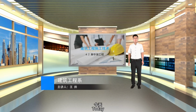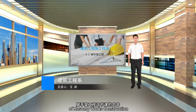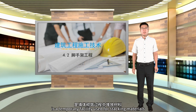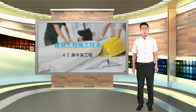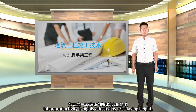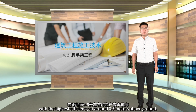Hello, everyone. Today, we will study scaffolding works in the chapter of masonry works construction. Scaffolding for masonry is a temporary facility used for stacking materials and providing a working platform for masons during wall masonry construction. When workers lay bricks on the ground or on a floor slab, labor productivity is highly affected by bricklaying height, with the highest efficiency at around 0.6 meters above ground.